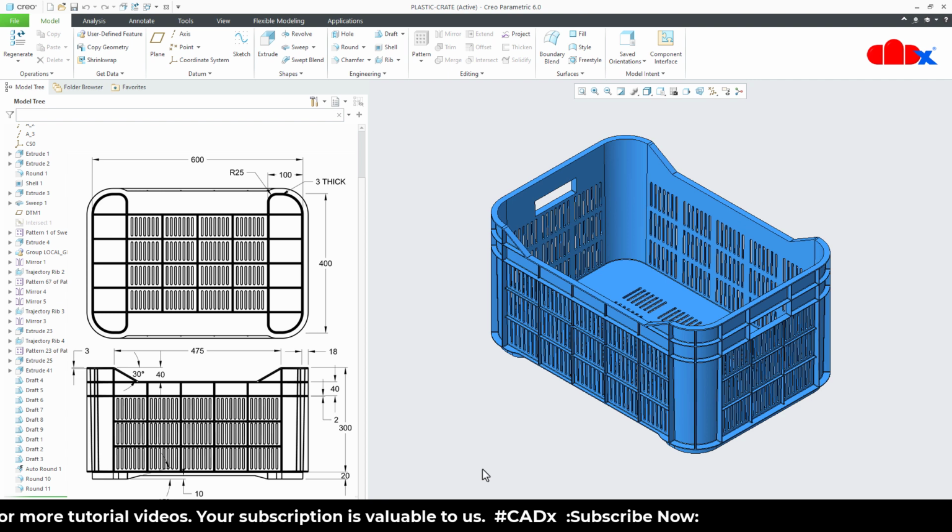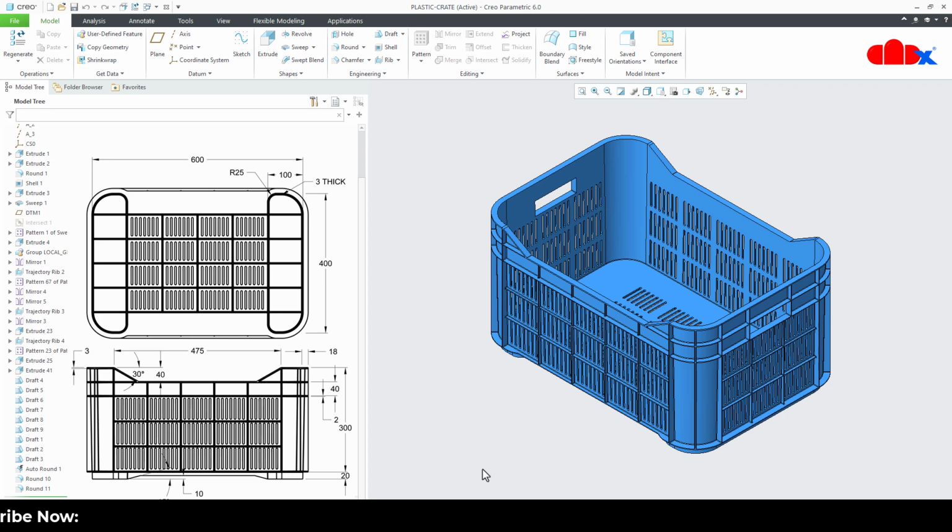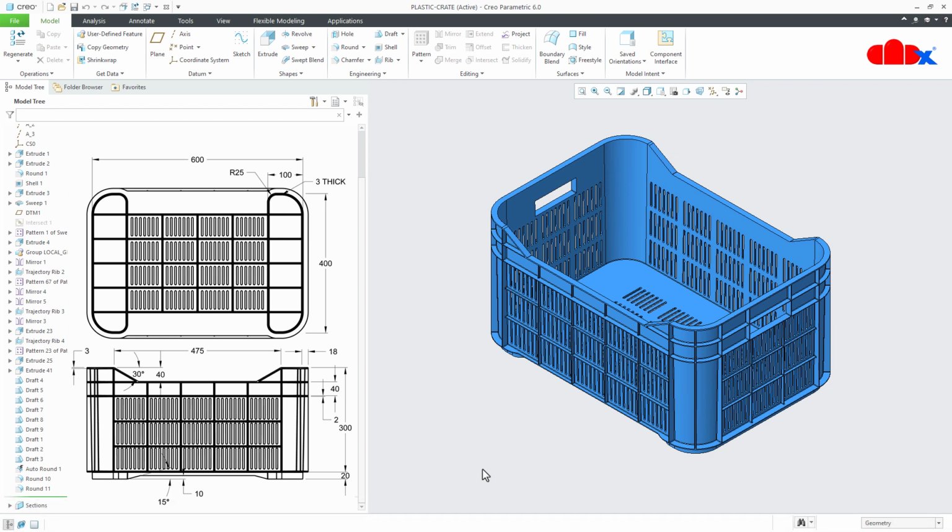Now the second parameter is uniform wall thickness. So for the plastic part, you must have uniform wall thickness all around, and this is strictly followed. So you cannot have variable wall thickness for the plastic part. Now when you see any plastic part around you, you will find that the thickness of all these parts varies from 0.5 mm to 2 mm. So why don't we have a thicker plastic part? So there are several reasons behind that. I'll just explain two very basic reasons.